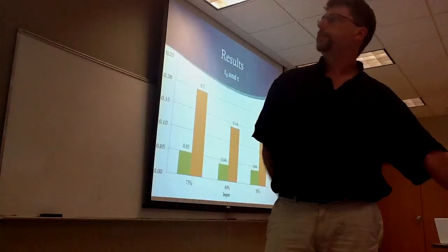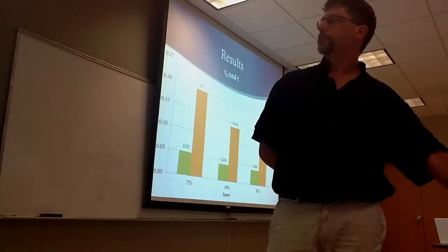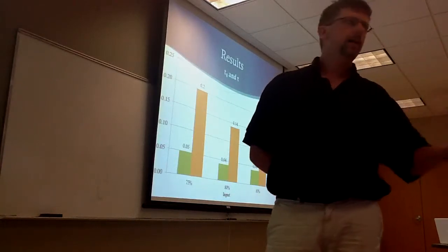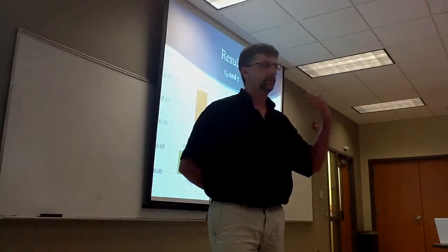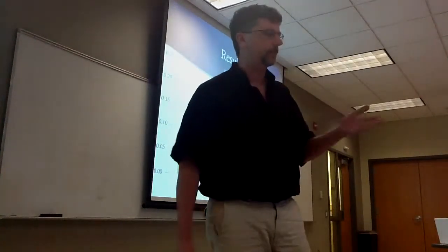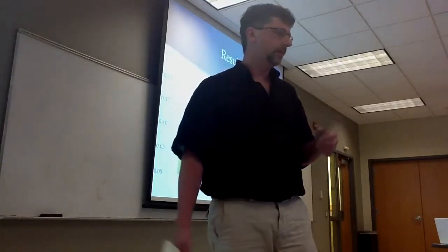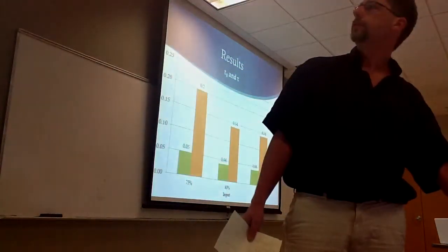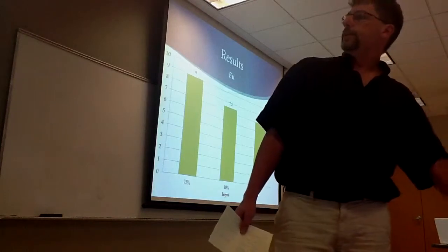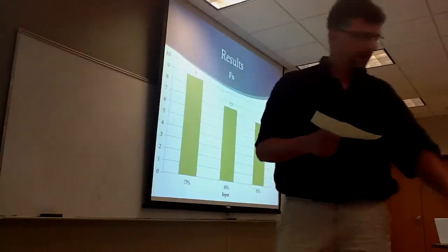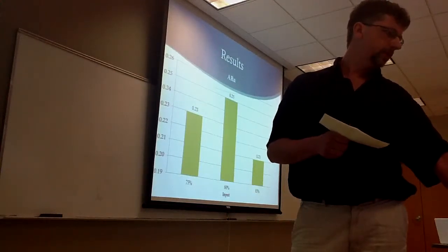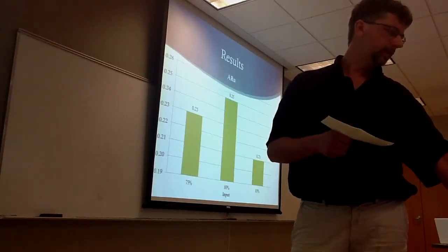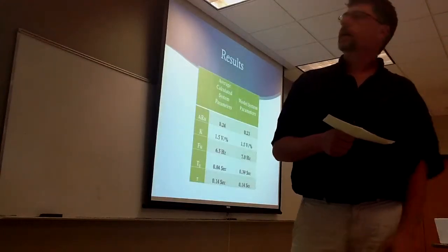Our T-naughts were very similar, and the taus, our range that we were operating in is very linear, and so the numbers that the three of us had for our 3 different sections of our range all turned out to be very similar to each other. The FU is 9, 7.5, and 7 for the 3 different ranges. Ultimate amplitude ratio, again, very similar for the 3 different ranges.